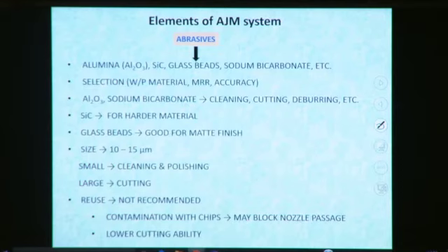If we reuse them, the chips will clog the nozzle and damage it. Because these nozzles are very costly, we don't want the nozzle to be clogged by this chipping action. So reuse of these abrasive particles is not recommended. Also, they have lower cutting ability because they wear out after some time.